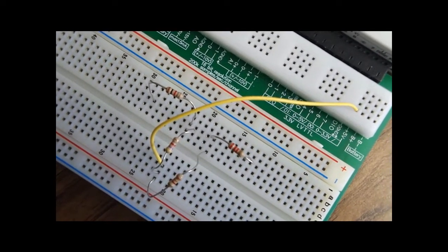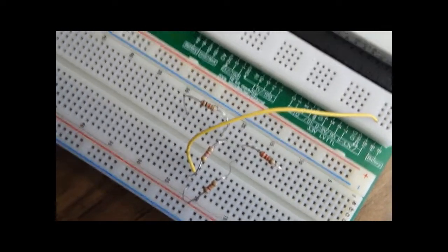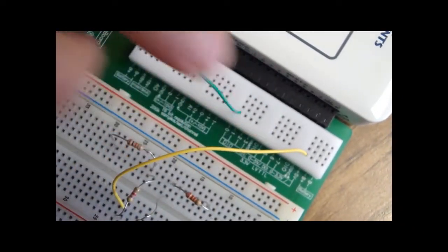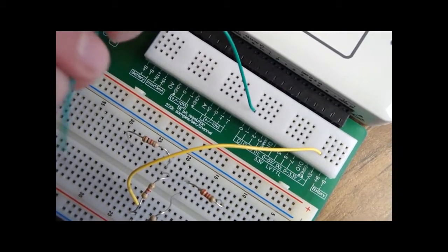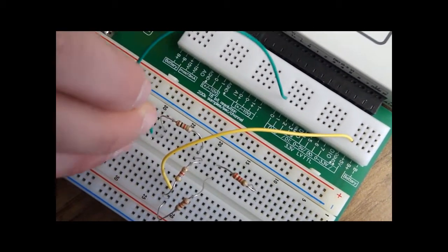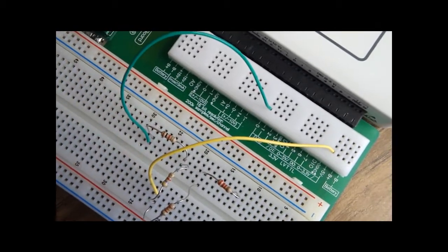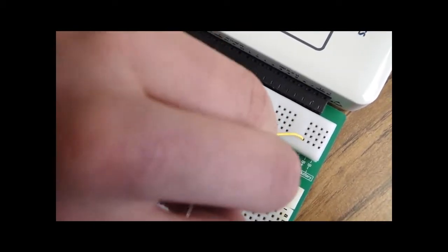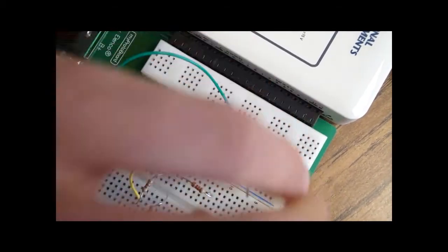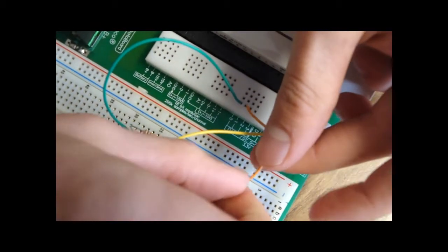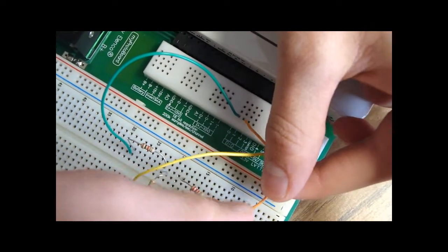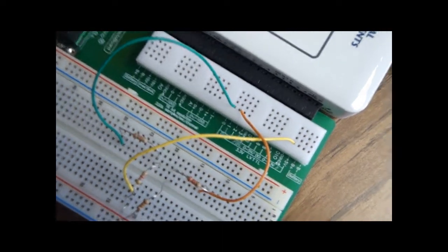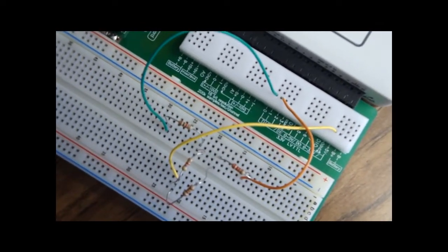So now the green wire is V1. We put it in DO0 and wire it to the left side of R1. The orange wire will be the V2 positive end, which goes in your DO1. You wire it to the right side, the positive side of R4. So this is how you need to wire your circuit in order for it to work.